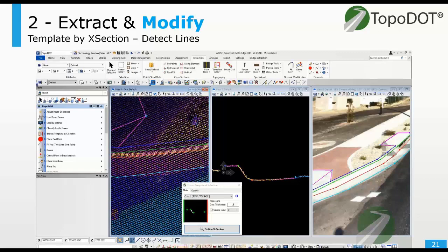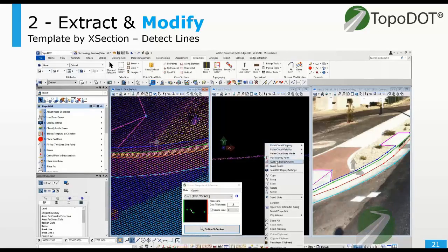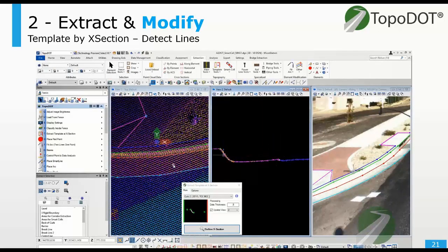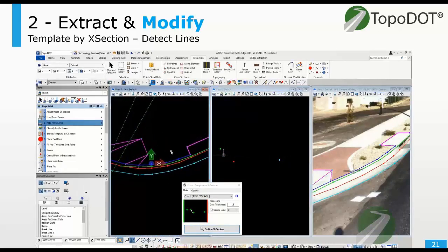Because as you drag the sample across, in this case I'm producing a large one, it's intersecting those lines, doing the fitment process, and then based off of those lines that it's intersected, if it has those common breakpoints, it's going to update the line work too. So if I just had a random default line in there, it would ignore it. So it does have to be compatible with those previous break lines.